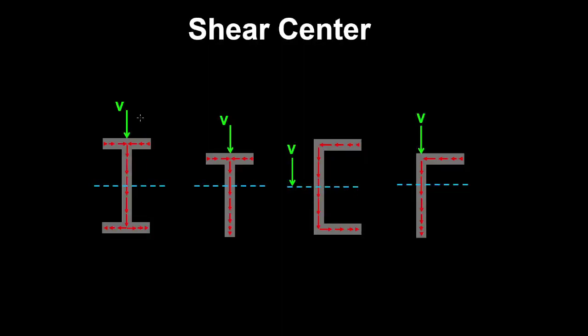The shear center is a point on the section that the shear force passes through and doesn't cause twisting of the section. And for example, if we look at this I-beam, it'll look something like this. And if a force is applied to it, where the line of action of the force passes through the middle of the section, then as you can imagine,